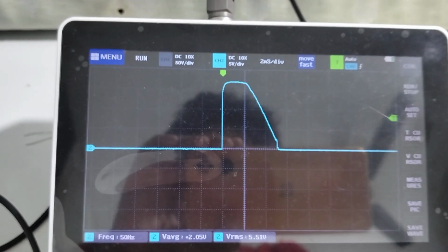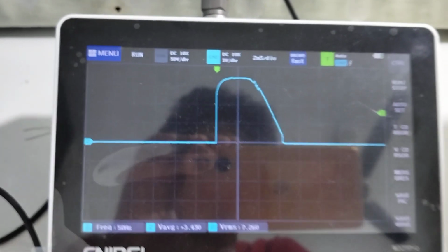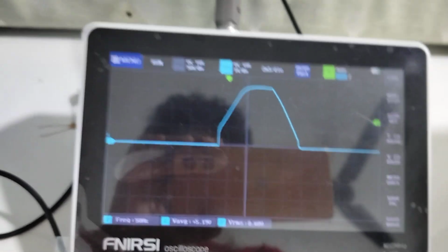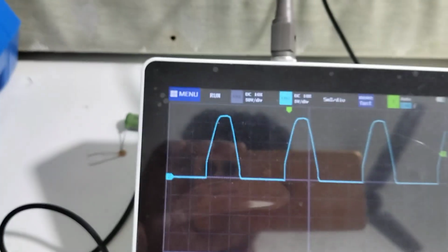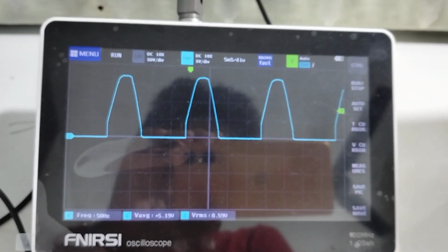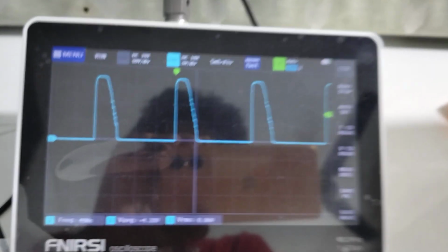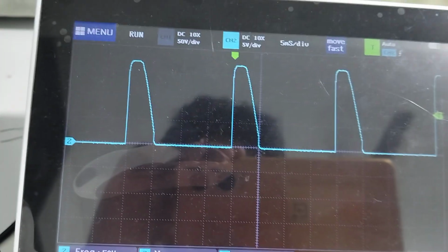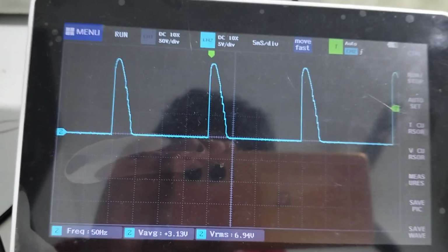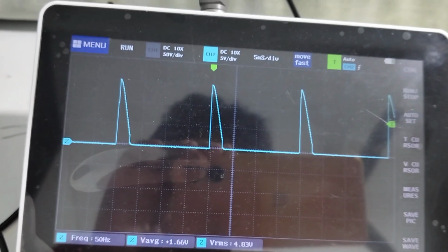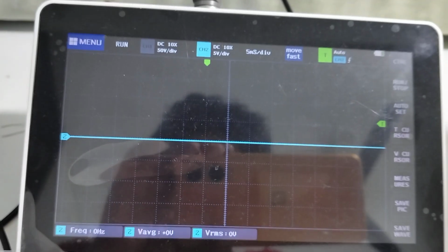So you can do that too, but let me increase the voltage again in the other direction. And you can see the RMS voltage is increasing again. So that was the whole point of the control rectifier here. By controlling the delay angle, you can control your average voltage as well as your RMS voltage. So we went low here just to show you once more. Now we just have a small peak here, and yeah, gone here.